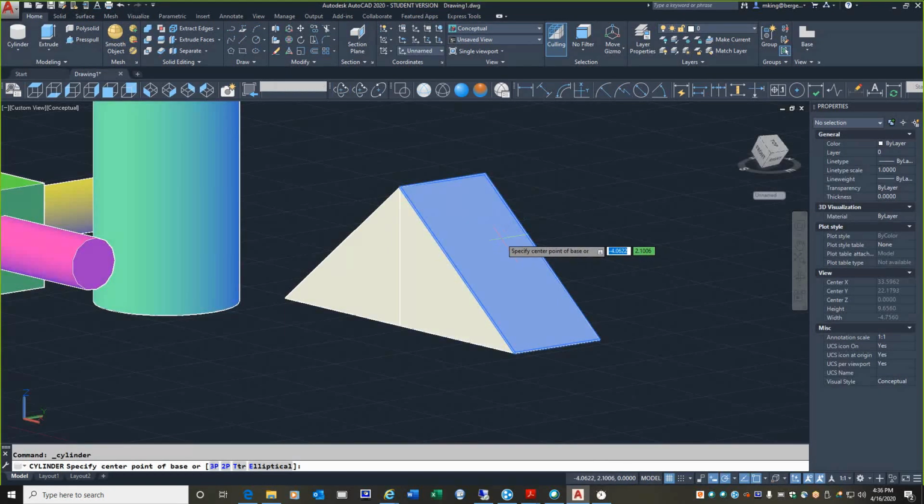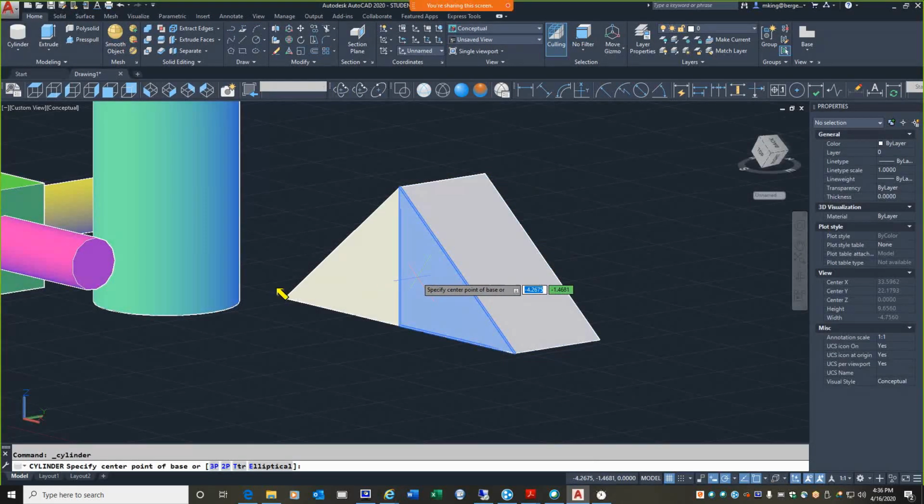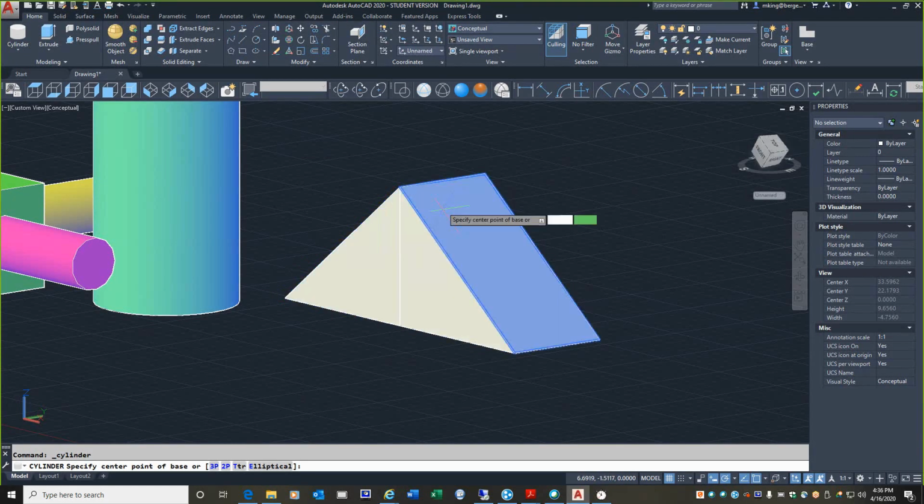Now watch what happens when I go around to the side face of this, and it activates that face. Look at my blue axis. It's now automatically pointing outward. So this establishes your work plane on the fly by positioning your mouse on the surface. Right? But here's where this becomes frustrating or a little more difficult, right? So when I bring my mouse onto the surface, I have to track to the midpoint. And if I do that on this side and I go out too far away from it, I just messed myself up. Now my wrong plane is activated. So I've got to go back to here.